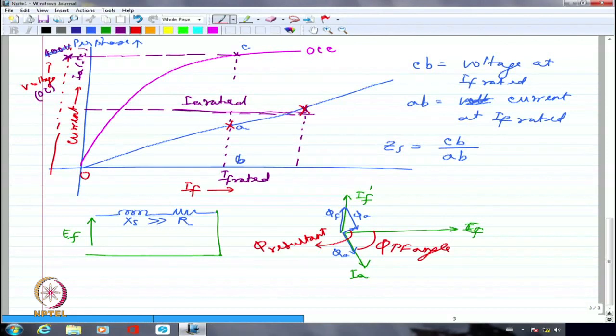If I am connecting it to an infinite bus, how can the voltage go to lower values? It cannot, because the infinite bus would say, you better maintain this voltage. So what has to happen is the generated voltage has to be increased. There is no other way. I repeat it. Infinite bus voltage is, let us say, 400 volts. If I am having a huge amount of synchronous reactance in the machine and the current drawn by the loads in the grid are all lagging, the voltage might try to go from 400 to 300 or 360. It will plummet. It will go down. But the infinite bus is going to say, you can't have lower voltage. It is not possible. If you can't have lower voltage, the only way is to increase EF.